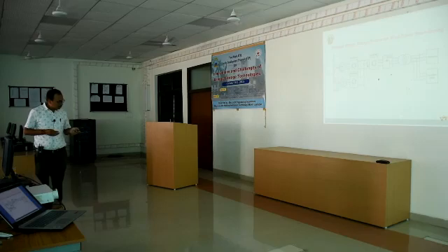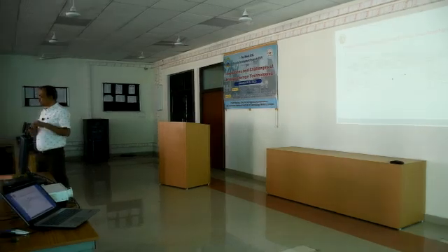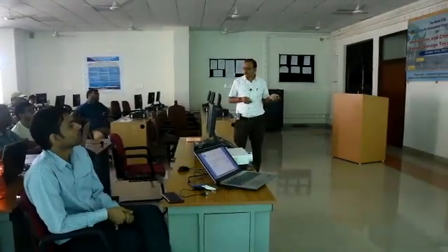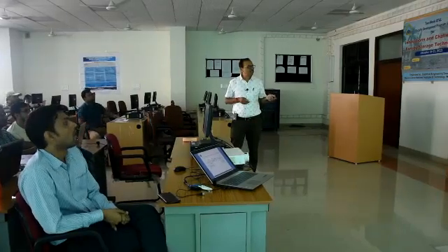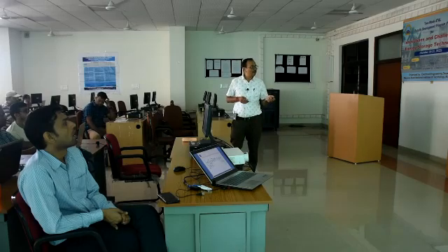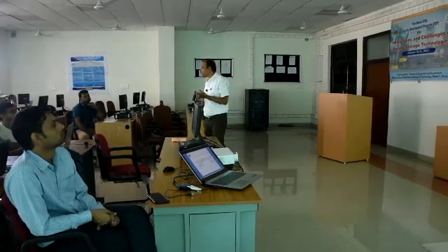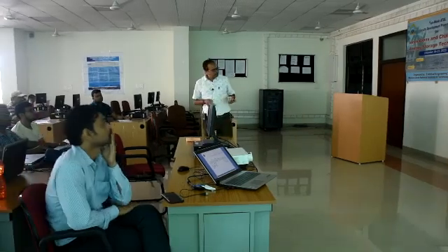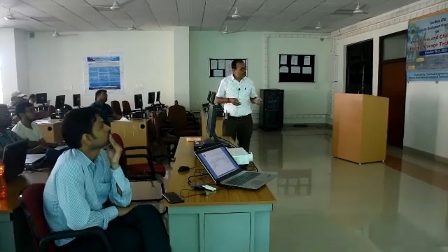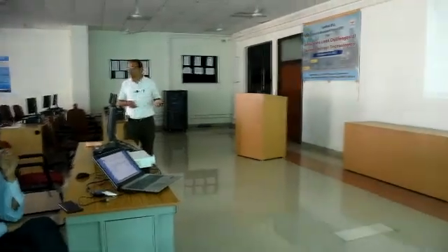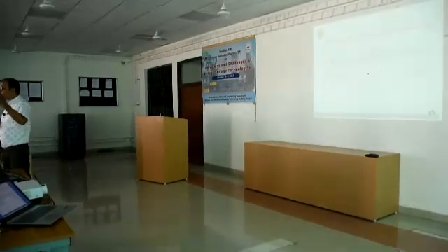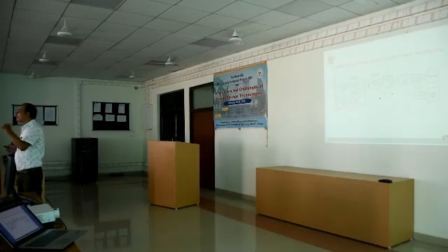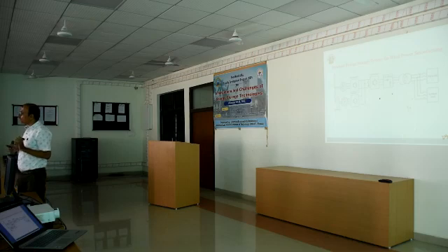Now, by the geometry of this wind turbine, even if the wind speed is constant, the power at this point is fluctuating. The fluctuating power is transferred to the DC link, and because you don't have energy storage here, we are using a capacitor, which is just to maintain the DC link voltage. So you will have the reflection of this fluctuating power at the grid side, and when a large number of wind turbines are connected to your grid, the effect will be cumulative, and you will have a voltage flicker in your grid supply, voltage flicker to your customers.